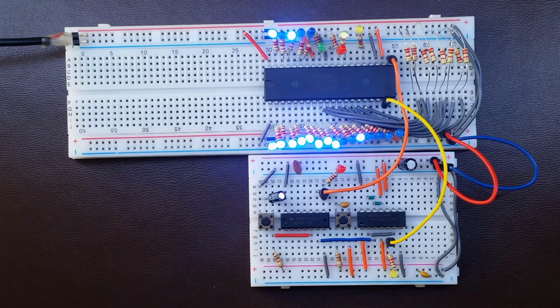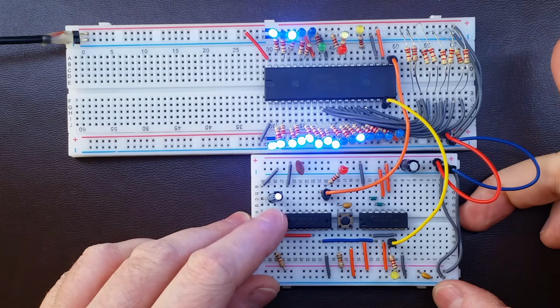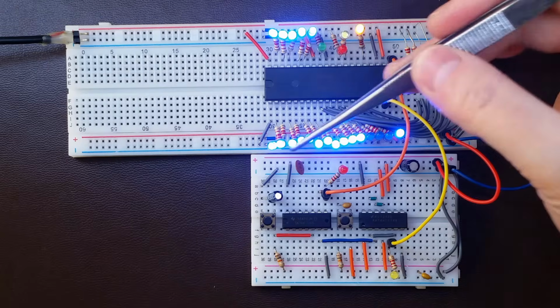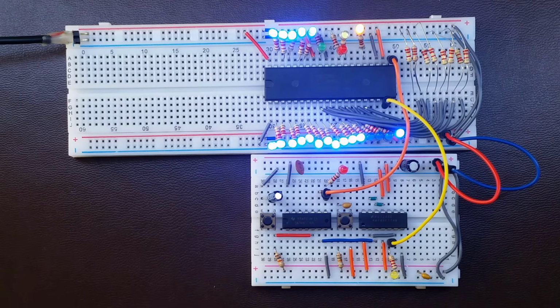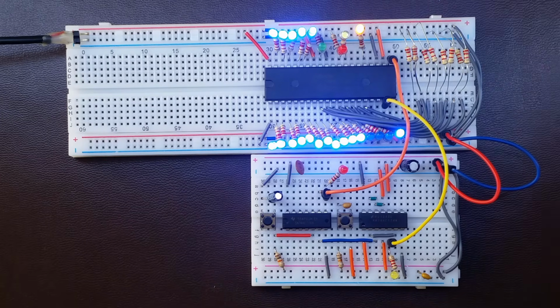Then we go back to the first cycle of the next fetch, and as you can see, all the address lines are now active. ALE shows that this is the address, but what's changed? Look at the least significant bit. Now we have FFFF1, because the NOP instruction does nothing, so our CPU tries to fetch another instruction, which is in the next byte.